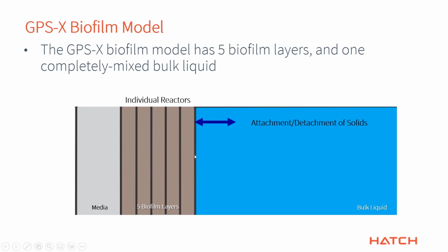So the solids will attach onto this outermost layer, and then of course some of the things are things that are growing in here. So we're going to produce probably a lot of inert material as this biomass dies. So that stuff is going to detach back off again. So now in reality, it's probably a little bit of a sloughing event, but we do it in a continuous kind of way so that you can solve it for steady state. Right. Okay. So that's the particulate part.